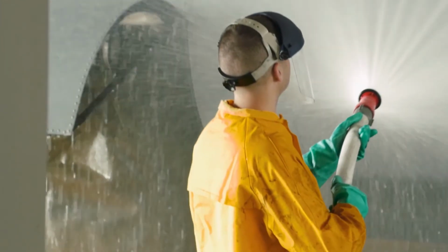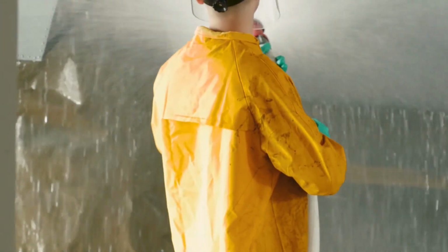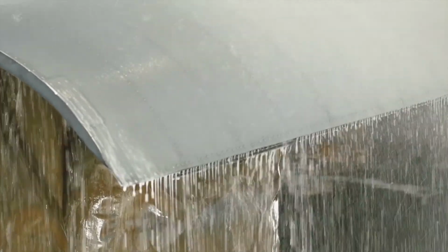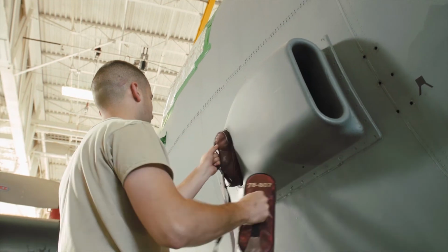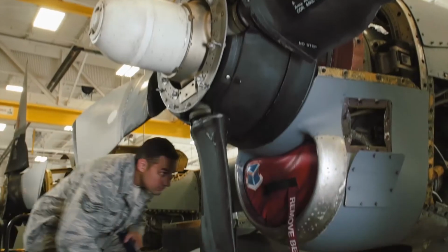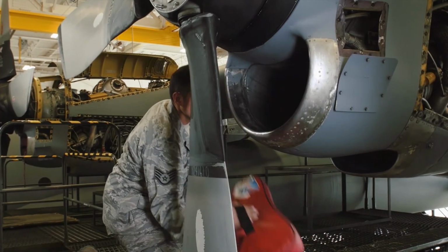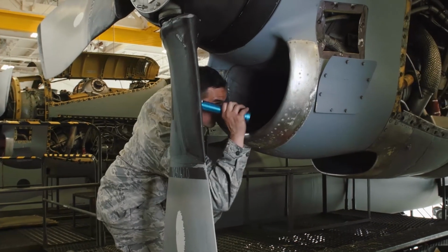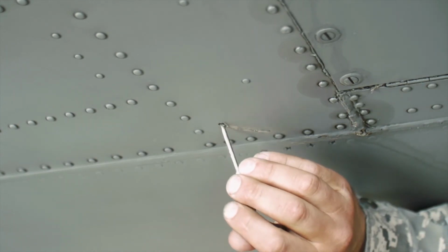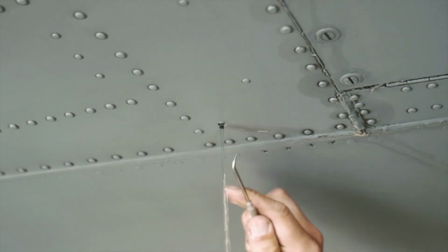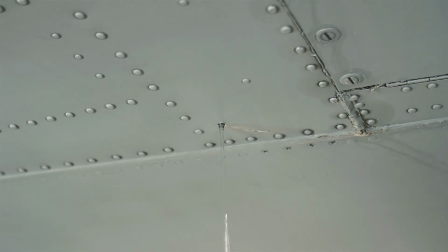Rinsing cleaned areas is as important as scrubbing them, since cleaners can severely damage coatings if not thoroughly removed. When you have completed the wash and rinse process, remove all of the protective covering and check areas where water can be entrapped. Likewise, you should ensure all drain holes are free of obstructions. It's very important that you remove as much water as possible from water traps, so you may have to open or remove panels or use forced air to dry these areas.